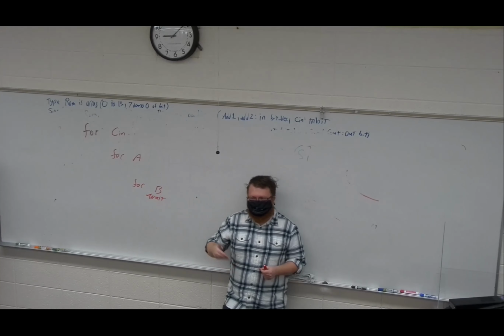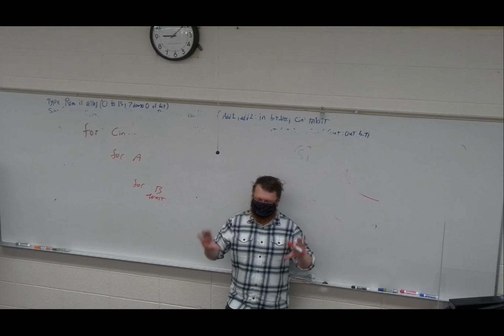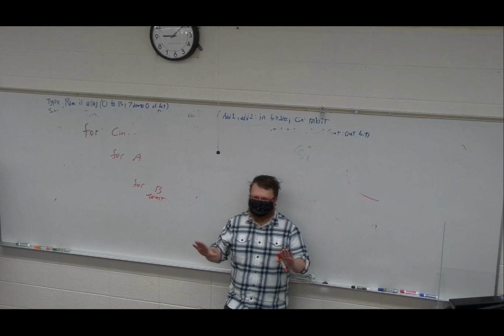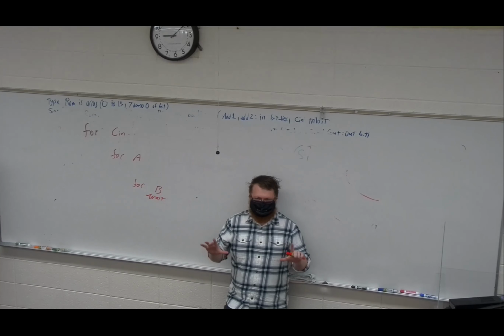Many of them didn't test their carry in. They just set carry in to 0 and ran their test and it worked. Then they built the 4-bit adder and expected it to work, but it didn't because their carry in wasn't behaving correctly. That's what I mean by test thoroughly.